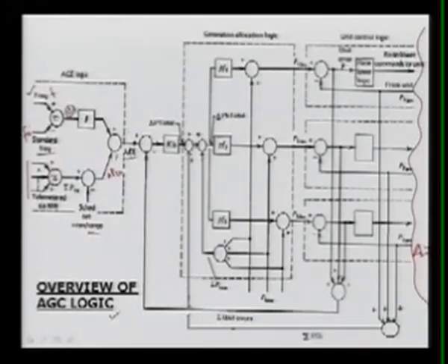So this is the ACE logic, the area control error logic. Here we are not going for optimal control, it is normal control, and we'll see how we incorporate the other base point loading. We measure the system frequency and the tie line power flows, and then we get the ACE. As you know, it is very standard, and we have already defined that ACE is your change in F multiplied by B plus your change in P12. Here again we write it with a minus because we are using the integrator, since for a change in frequency we require more power.